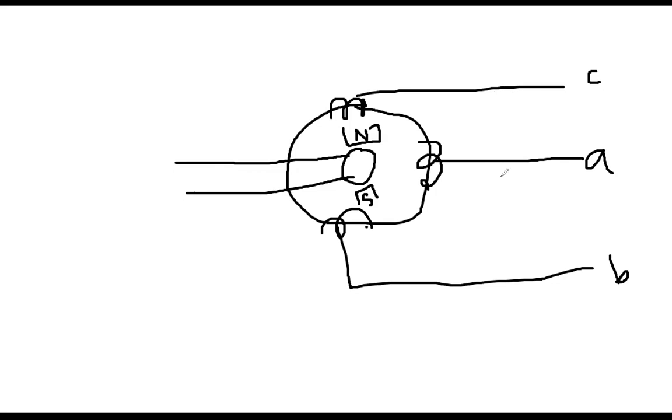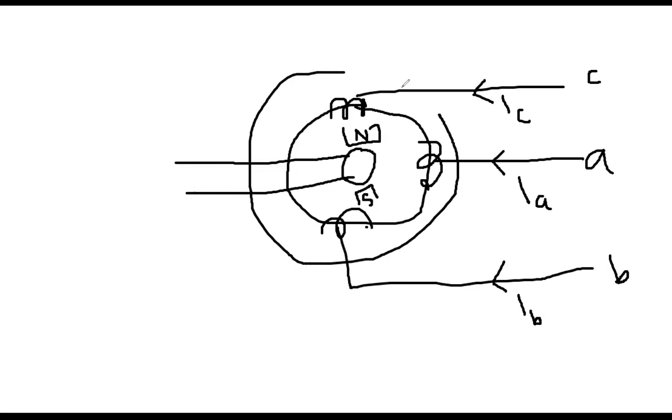Now, okay, everybody come back. Because this is a motor, what do we have to do? I have to apply the voltage, which means I have to apply the current. So my A phase current, B phase current, C phase current are going into the machine. Once I apply the three-phase voltage or currents to these coils, exactly the same thing happens that we learned for the induction motor. It will produce a rotating magnetic field, phi s. And what will be its speed? The same as in the induction motor, synchronous speed, ns = 120 f / p. Exactly this will be the speed of that magnetic field.